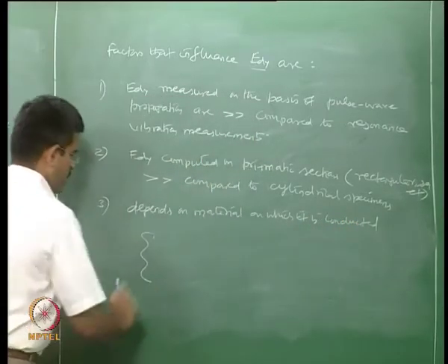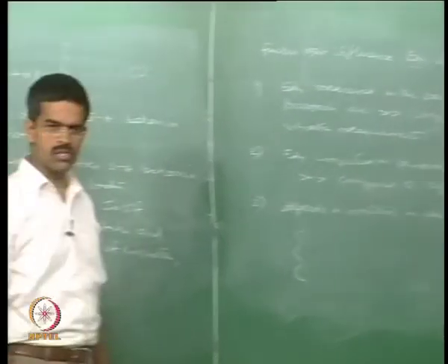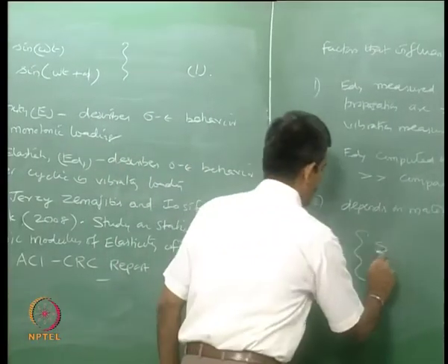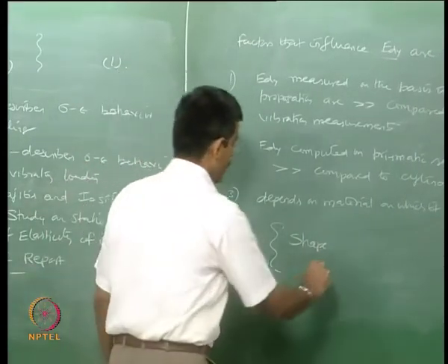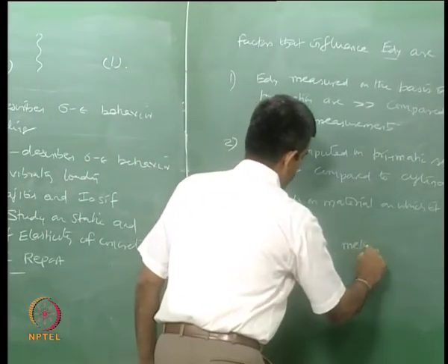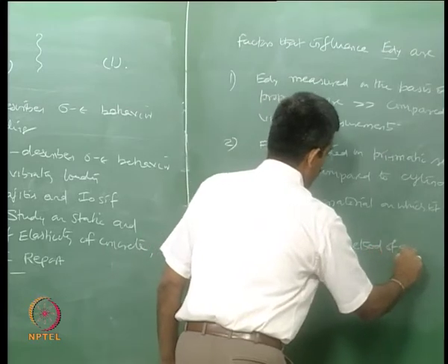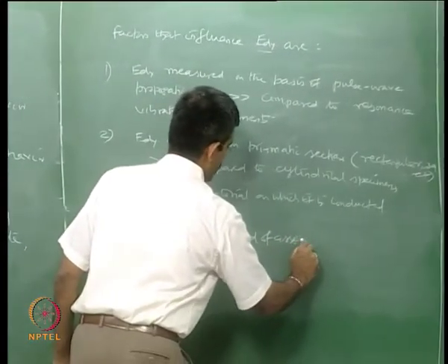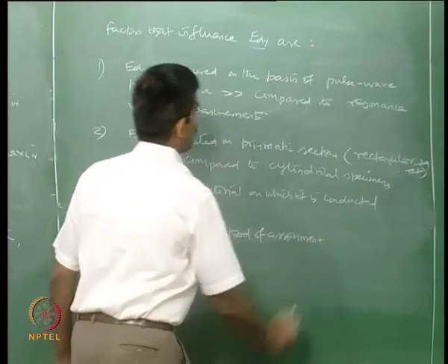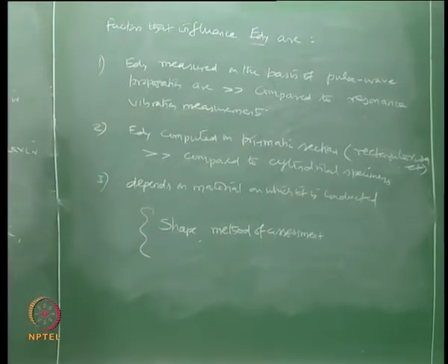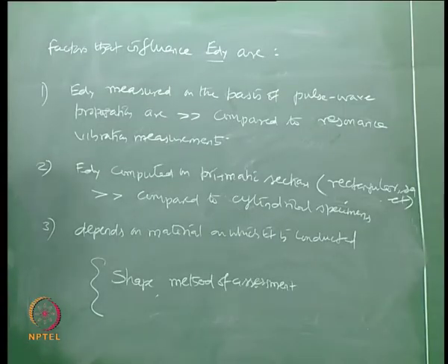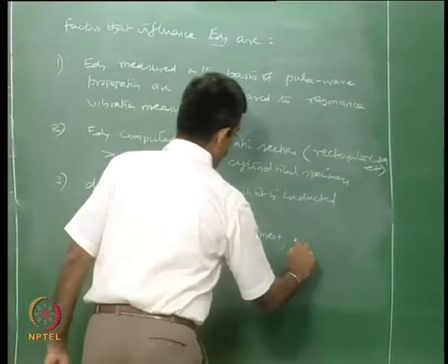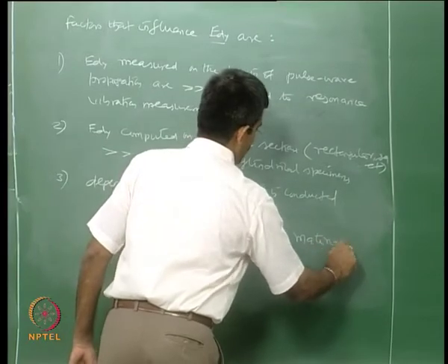So, one can say the factors influencing dynamic modulus of elasticity could be the shape of the specimen taken for the test, the method of assessment, whether you are using the pulse wave propagation technique or the forced or free vibration method on resonance condition, etc., and of course the material characteristic itself.